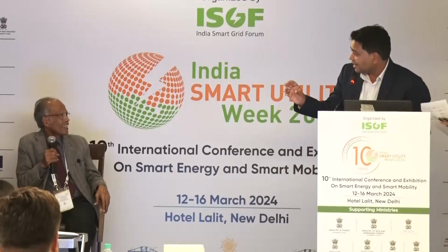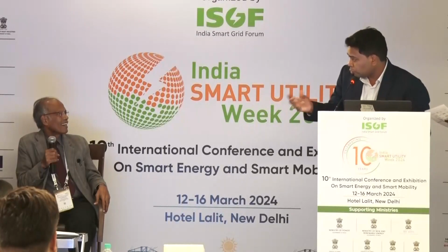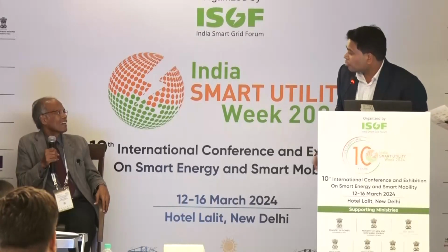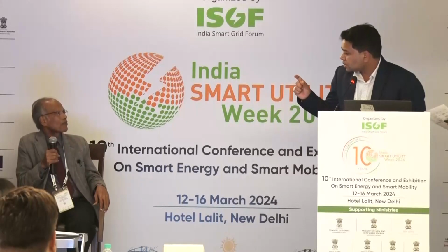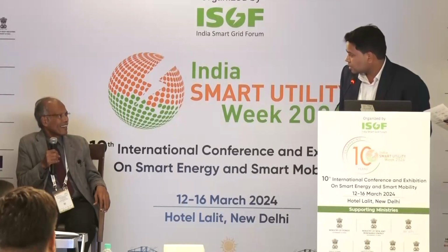Very nice. And what about the patent? Would you have done it for this particular process? The eco gas mixture does not have a patent. The fluoronitrile mixture was basically prepared by 3M. They had a patent, but now it is available for public use. Many vendors and OEMs like us are using that fluoronitrile and adding some more gases like nitrogen and O2 in different proportions to meet the performance range demanded of that equipment. But fluoronitrile was 3M's, called Novec gas, and that was patented by 3M.